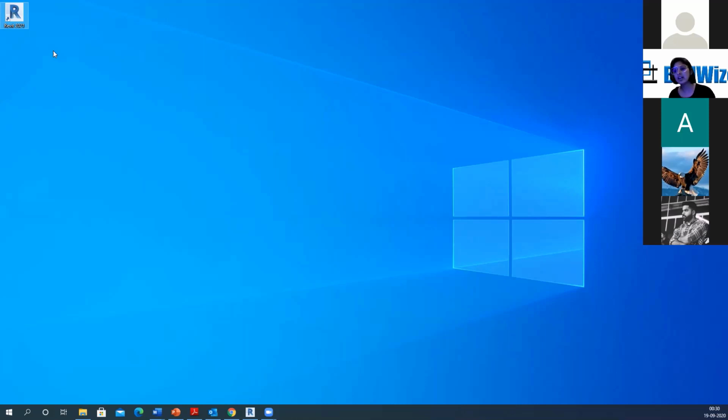do not directly click on the file because there are chances that the file is in a different version and you upgrade it or do something to it. The best practice to open up any project in Revit, or any Autodesk software, is that you launch the program first. So whatever version you have, and let's say your clients or your teachers have given you, or even I give you an exercise file, you should be launching Revit first. Revit is being launched on my other window. I will share that window with you guys, right?